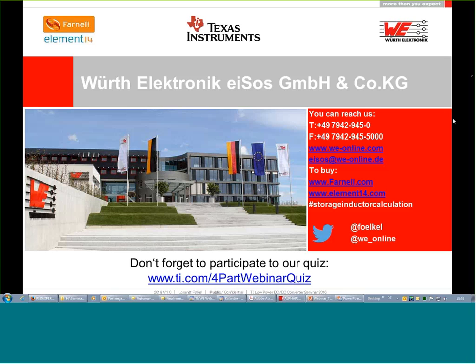And additionally, at 10 megahertz the inductor will be very, very small. You will never need 100 microhenry at 10 megahertz; 100 nanohenry is already enough. It's a very small inductor indeed, but you will have to fight again for the EMI. And then the EMI filter will also affect the efficiency as well.